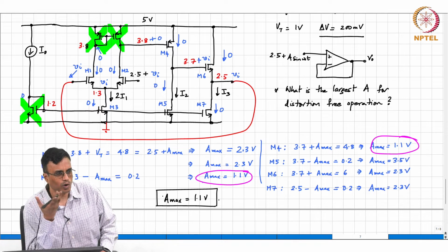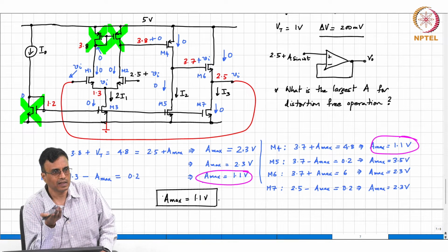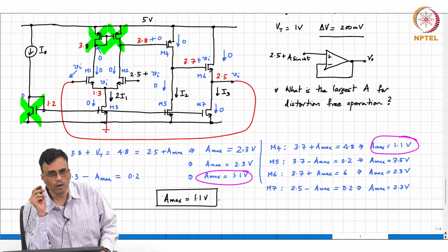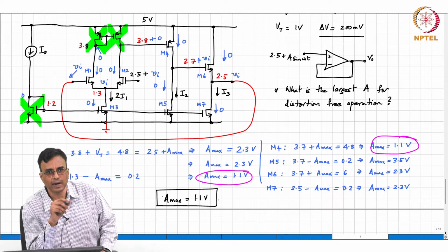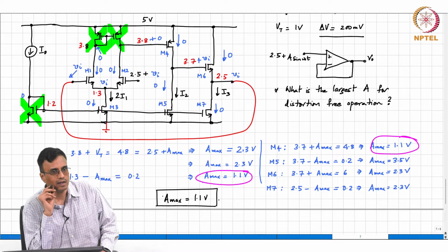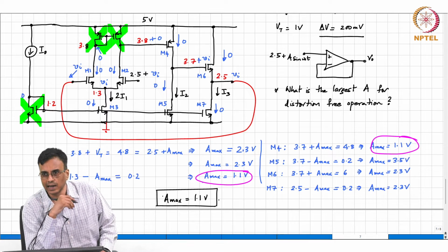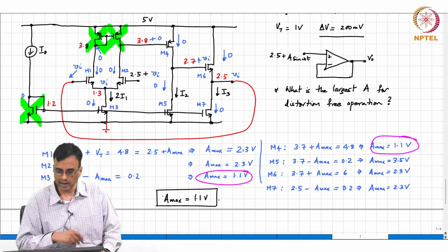As you can see, there is no rocket science here. This is the same thing that we have been doing for all the single transistor circuits. First job, find the operating point, then replace all transistors by their incremental equivalents and do the small signal analysis.